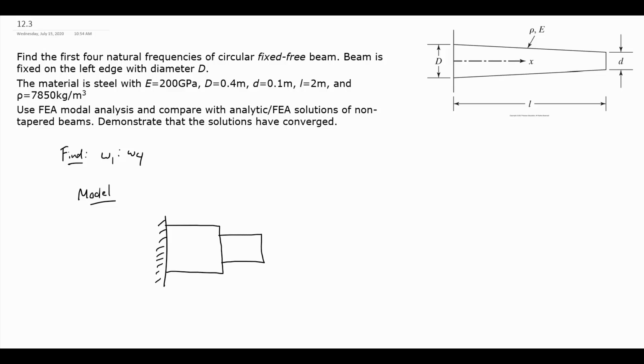I'll just illustrate here with three elements. So we have this very coarse-grained mesh here, so it's a very blocky descent. But as I keep adding more elements into this system, and the elements are getting thinner and thinner, what we're going to see is that as we go from one element to the next, we're going to have a much smaller step change in the cross-sectional area and the area moment of inertia, because the radius is going to be changing more rapidly.